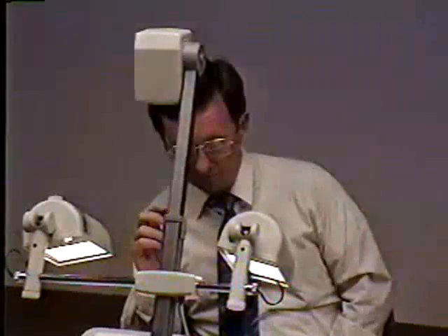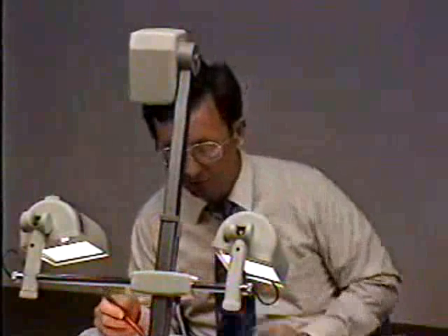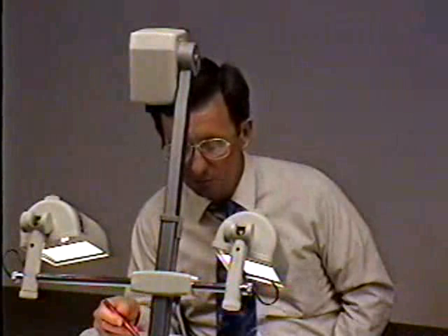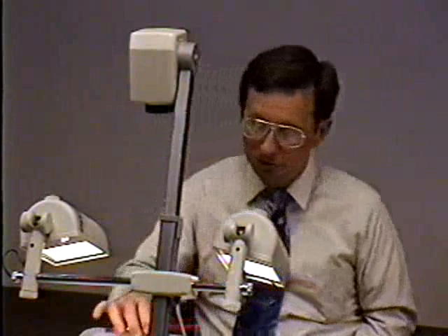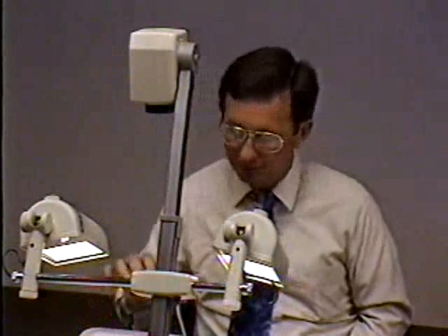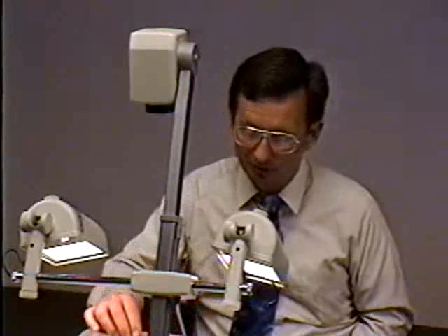So the basic procedure that's been used for decades is you set the rainfall duration equal to the time of concentration of the watershed. And then you assume you've got an equilibrium of what's falling down is coming off, except everything's not coming off the watershed because some of the rainfall is lost through infiltration and the other hydrologic abstractions. So the C is a dimensionless number that tells you what's coming off. That's just the proportion of the rainfall that actually runs off of the watershed. The rest of it's lost through infiltration, etc.